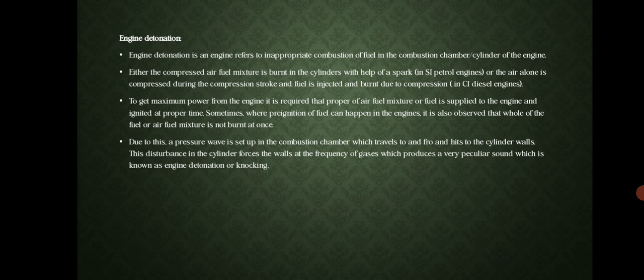Sometimes pre-ignition of fuel can happen in the engine, and it is also observed that the whole of the fuel or air fuel mixture is not burnt at once. Due to this, a pressure wave is set up in the combustion chamber which travels to and fro and hits the cylinder wall.